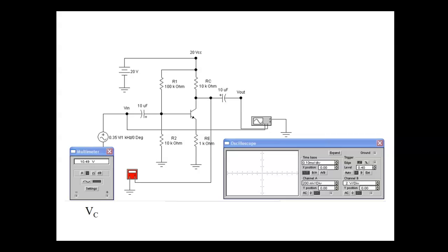Are you going to have to ever calculate these voltages when you get out in the field? Probably not, because normally schematics do that for you. Right? But now you understand why it's there, right? This is why we do a lot of computations in these classes. And like I said, it concerns me where you calculate one thing and you measure another, and then you just move on. Like in DC, you've got a series circuit, and you measure 0 volts, and you write 0 volts down, and you know it can't be 0 if it's a series circuit, right? So that's the kind of stuff we're trying to teach you.